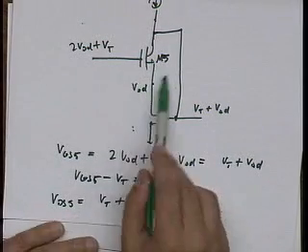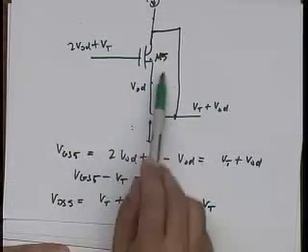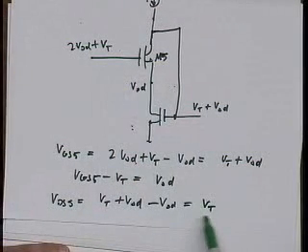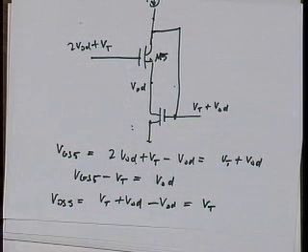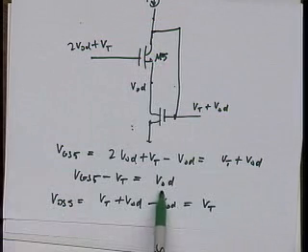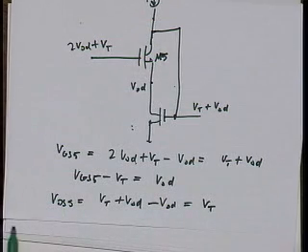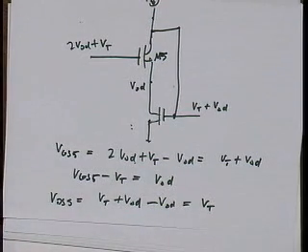So this transistor M5 will remain in saturation as long as, again using square law theory, VT is larger than V overdrive. Okay? So we have to be careful to make sure that this is actually satisfied for our technology. But if we're putting this at 100 millivolt overdrive and our VT is 300 millivolts, then clearly that's a safe bet. All right? Questions or comments?